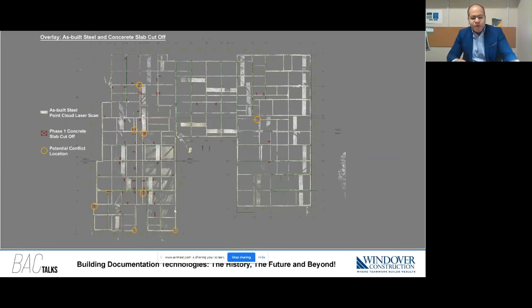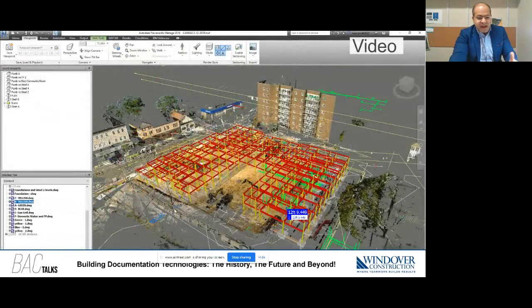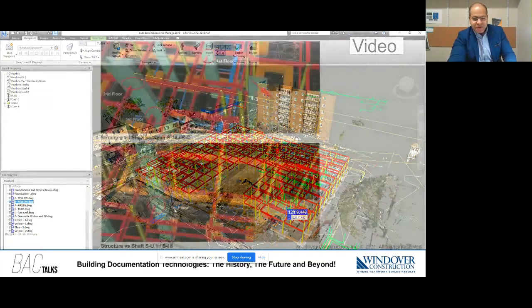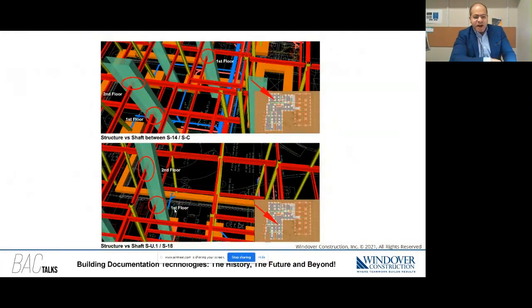So we made sure this way to detect a dozen clashes in real time, communicated to the factory so they could make any necessary adjustments. And with that, we made sure that all the boxes, when they arrived on site, had 0 clashes. That's a mixture of drone mapping, laser scanning, and BIM data, plus, of course, the MEP BIM coordination, which you've seen here on the screen. These are the clashes we found, where steel is hitting the vertical shafts.